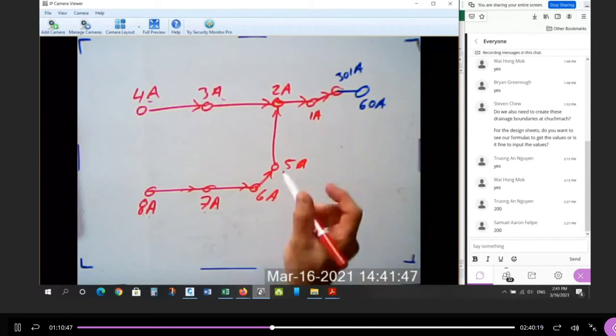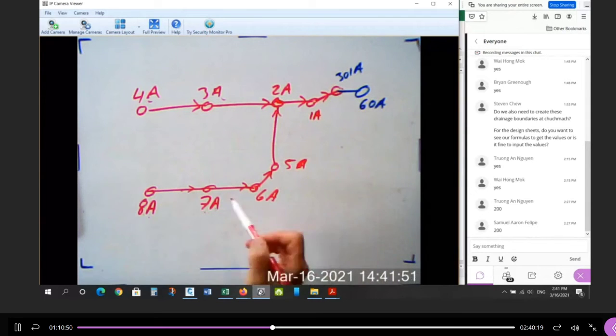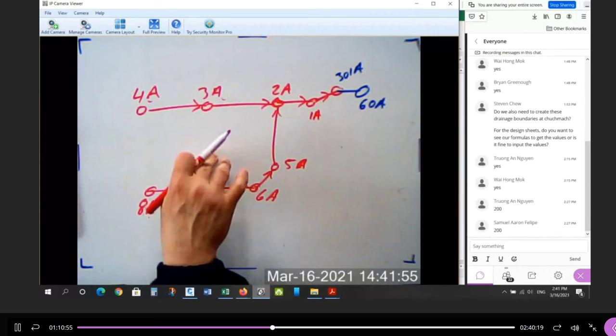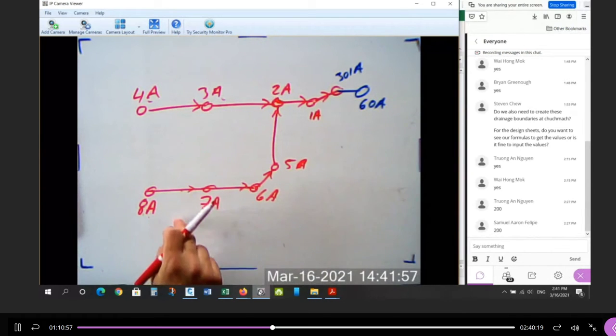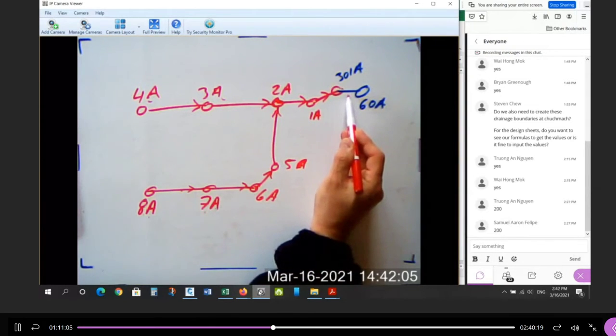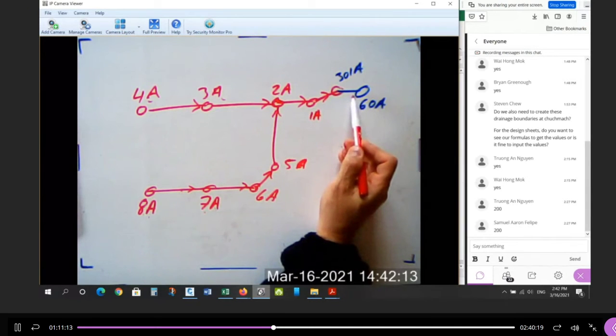And eventually out, right? I just need to check that this pipe still has the capacity for this area. And I'm not worried about it for a couple of reasons. One, I went from commercial to residential, so I'm expecting lower flows because of that. And I know that this pipe was sized for commercial, and now I'm going residential. So the expected flow in this pipe should actually be proposed less than it was before.